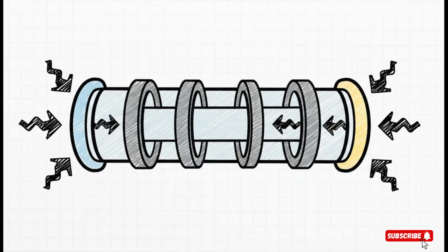And this right here is the absolute most important concept we need to grasp: electrical isolation. Think of cathodic protection, or CP, as a system that pumps protective electrical current from the soil onto the pipe. But for that current to actually get to the pipe's surface, the pipe has to be completely electrically separate from that outer casing. We do this with plastic spacers that keep the two pipes from touching, and with rubber end seals that keep dirt, water, and debris from getting inside and creating an electrical bridge.